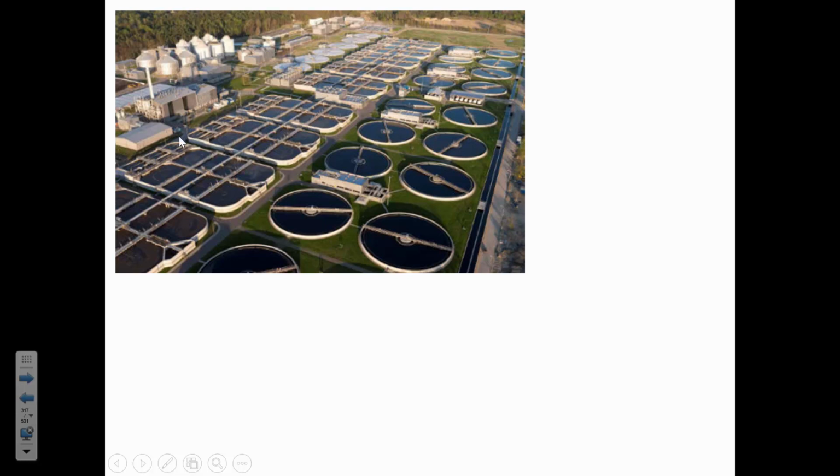These basins are aeration basins, and they're shaped in such a way that the wastewater goes through, and underneath the water at the bottom of the tank, there are these diffusing stones, similar to what you'd maybe see in a fish tank. And the purpose of those diffusing stones is to provide oxygen to the bacteria that is in these aeration basins, because the bacteria break down some component of the wastewater that would cause a lot of problems if it got into the river.